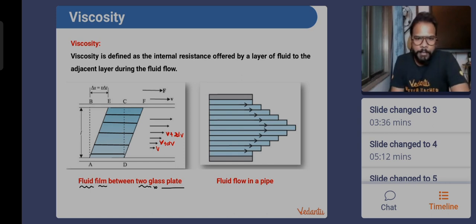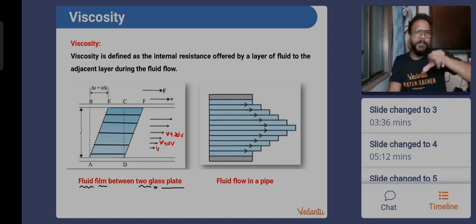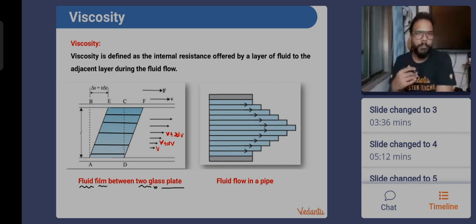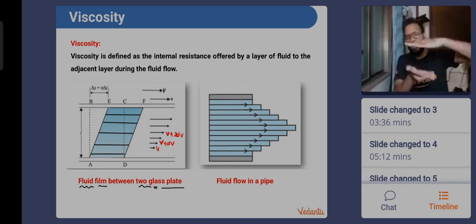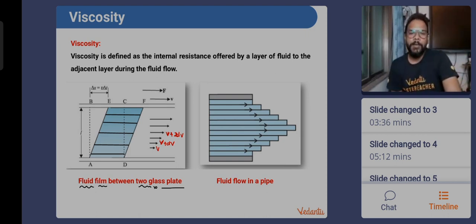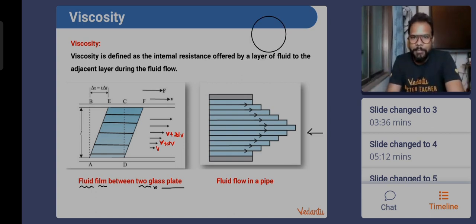So guys, there is one important point that we need to look at in the two diagrams that we see here. The first one is the side view. Both of these are side views, by the way. Say when water is spilled on a floor, the topmost layer will move very easily, and the bottommost will move with most difficulty. That is the first one, when the liquid is allowed to move on a floor. Here they are talking about two glass slabs between which the liquid is placed, but more or less what they mean is this. The second one is liquid traveling in the form of cylindrical layers in a pipe. If you look at it from here, this is how the liquid will appear to you. Not actually, but this is how you will visualize the layers.